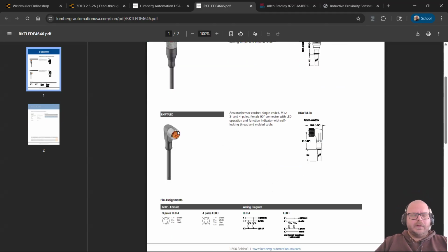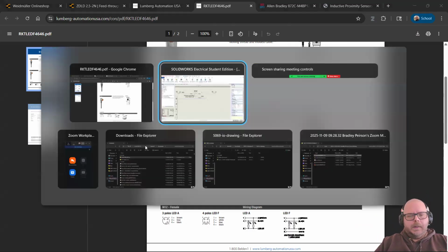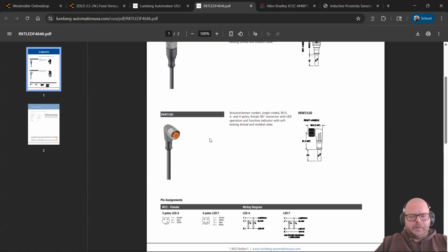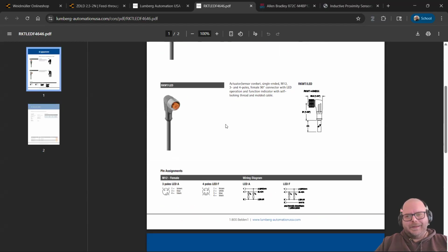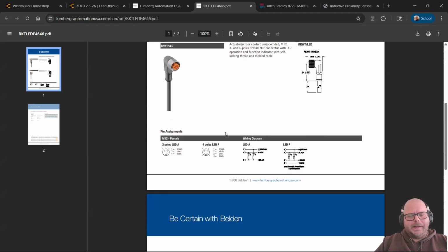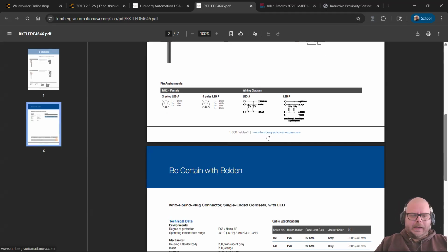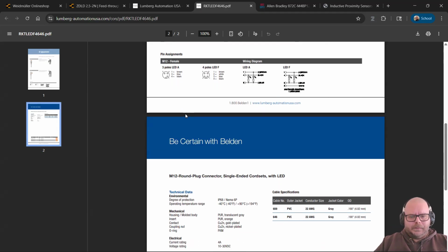That's the other thing. Using cable sort of requires you to have in your head a physical view of where everything's got to go. With a single-ended cable, it's not so important. We just need it long enough to get there. We can always cut it. A double-ended cable, we definitely have to have an idea of how long we actually need. We can always wrap up extra, but we don't really want to cut a factory cable end off and then splice it onto a shorter cable. So we need an idea of lengths. That's an idea to keep in mind. We can't really get that just from the electrical schematics. It's a thing we just have to sort of work through.